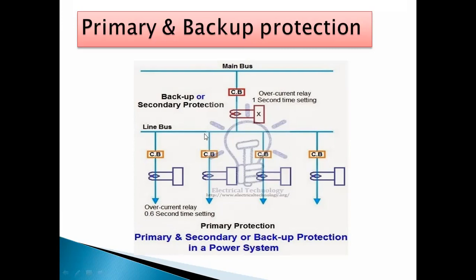Here you can see the time setting is there. Time setting means when your fault will occur, at the time of 0.6 seconds, this relay will operate. But when this relay will operate for this backup or secondary protection, its time is 1 second.